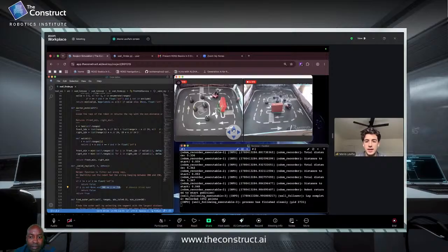One case that we took into account for those types of cases is that it's hard once this outer wall approach fails, for example once the robot starts facing a corner. What happens in this case is that the robot gets close to the corner and finds two outer walls at the same time, so it can get distracted in terms of which one to face.